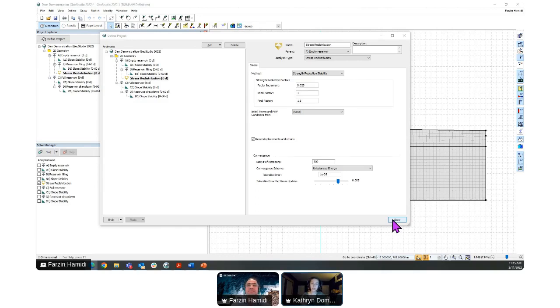It's really easy in GeoStudio. We hope this demonstration shows that it's easy to have a project file with one single dam cross-section, and super easy to add all the different analyses to the same project file and compare the results. You add an initial conditions SEEP W analysis, put in a SLOPE W analysis to look at your initial stability, throw in a Sigma W analysis to look at the constitutive models and the stresses, and then compute the stability using those stresses.